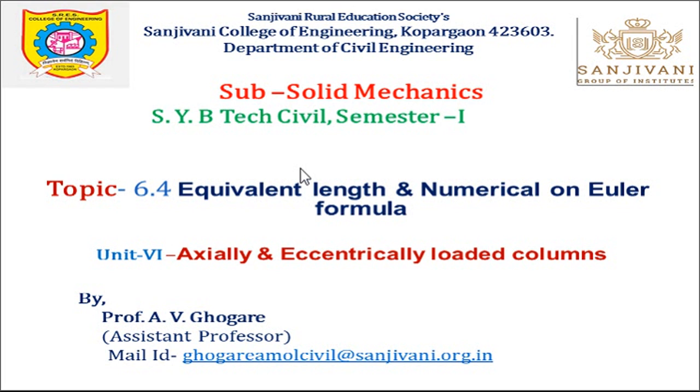Up till now, in the topics we have studied about axially loaded columns, we have studied the different types of columns, simple short column, medium column and long columns, and also the different stresses induced in these columns, and also the failure criteria of the different types of columns are important. Basically, the short columns fail due to crushing because of the compressive load. That is the major important factor for the failure of the short column.